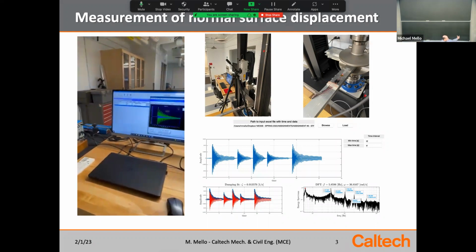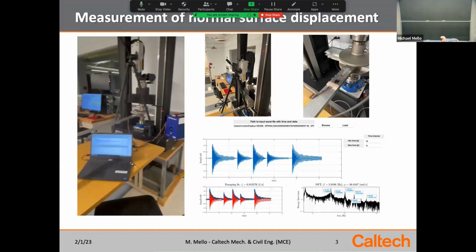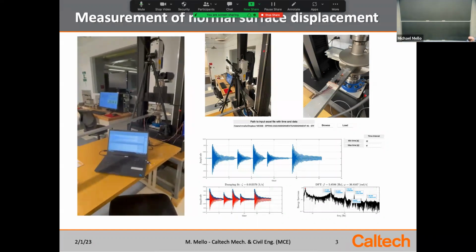So we had both strain gauges and the laser vibrometer producing these ringing curves that you see here. We would literally flick the beam, let it ring, and its oscillation and dominant frequencies would drive that signal, and then it would subsequently decay due to damping. What you see are just multiple attempts at us flicking the beam. Those repeated blue curves are us flicking the beam, having it die out, letting the device continue to collect data, and flicking it again.